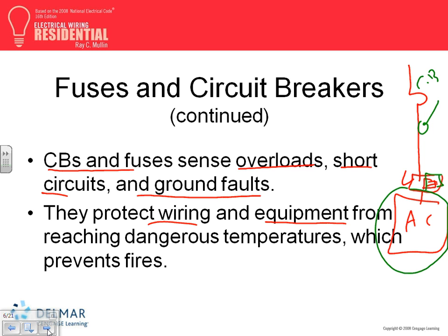It is special protection for the equipment. Most equipment, guys, high-profile equipment, is going to have its own protection. So what does this circuit breaker do then? What this circuit breaker is really doing, in reality, is just protecting my cable from here to here. If you have any short circuit, overload or ground fault in this section, my circuit breaker is responsible for it. This piece of equipment will be fully protected by the manufacturer-provided fuse disconnect.